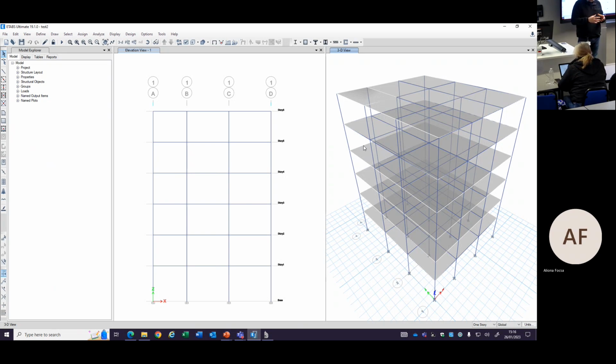Concrete, at the beginning, starts to crack. We have many problems with cracking, not this kind of crack, but the cracking in the design for bending moment. So the majority of the section goes out of the game, and you will count on a very small part of the section in compression and also the steel. And the interaction between the steel rebars and the concrete is a problem as well. You have many issues like this, but in steel structures you don't have these kinds of problems. Still, you have a different kind of problem we talked about last week, which is buckling.